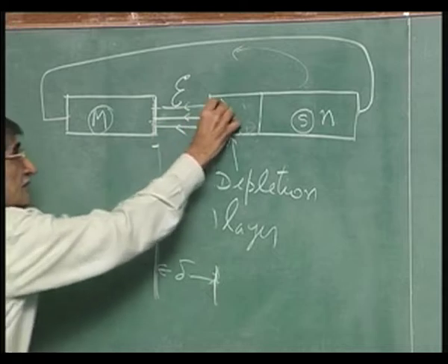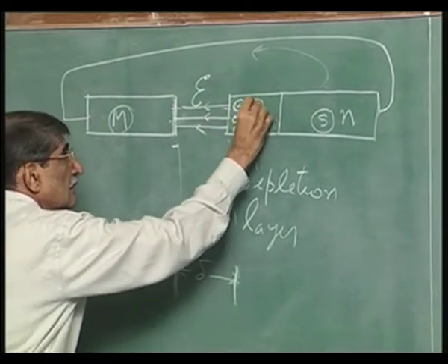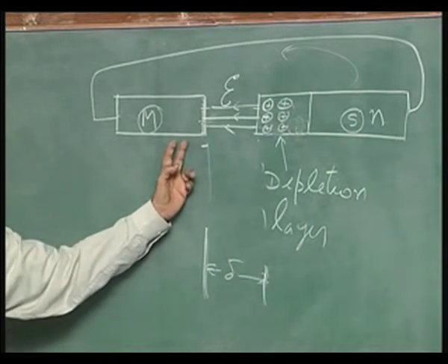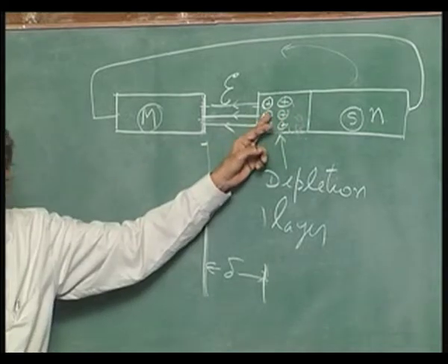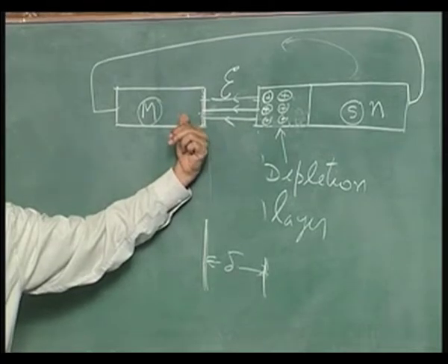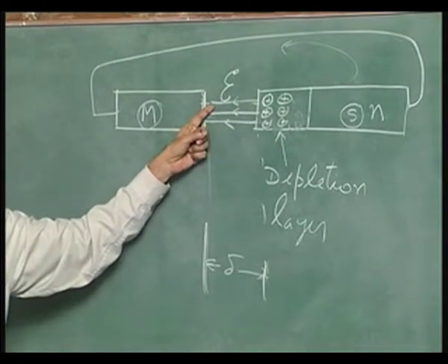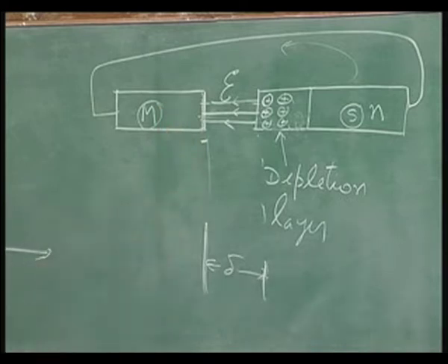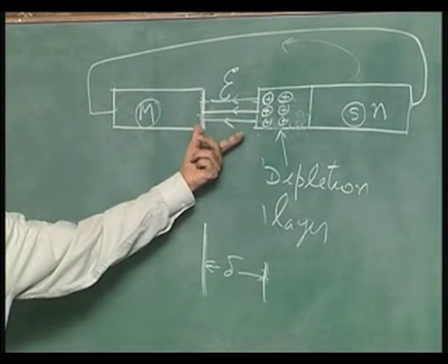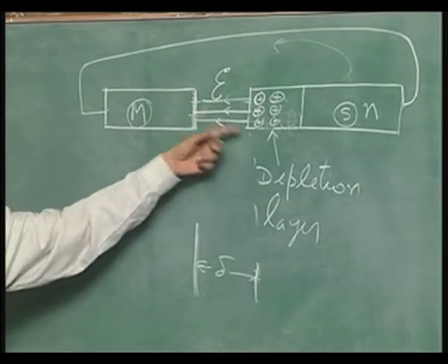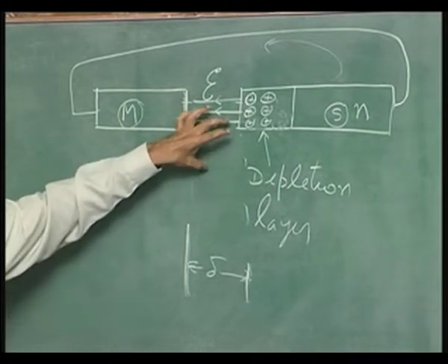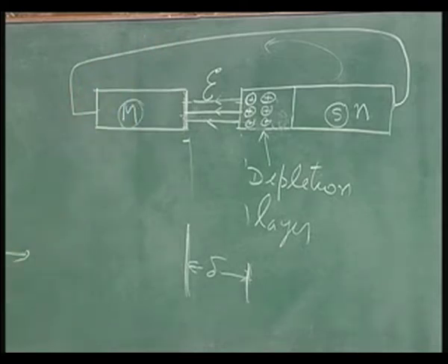The number of electric field lines which cross will be equal to how many electrons have moved from here to here. For one electron which has moved from here to here through the outside wire, you have got one positive charge and one negative charge. So, that is one field line. Once you have connected them together, the charge here and charge here is fixed. That means the electric field here is fixed. How much is the potential drop here depends upon how much is the gap. Electric field into the distance here is the potential drop, linear. That is what is put here.